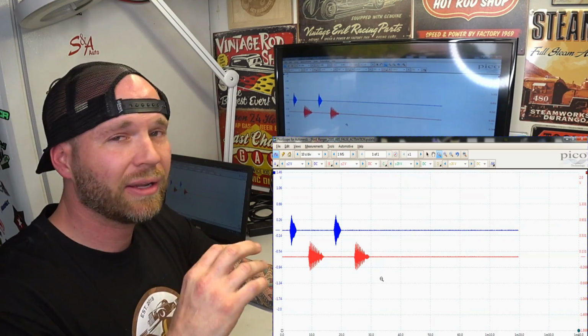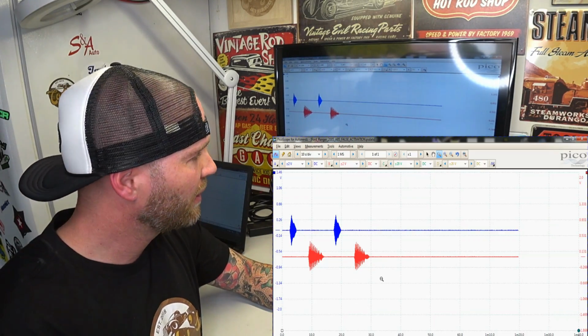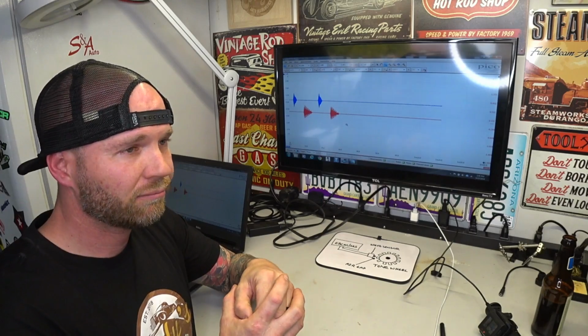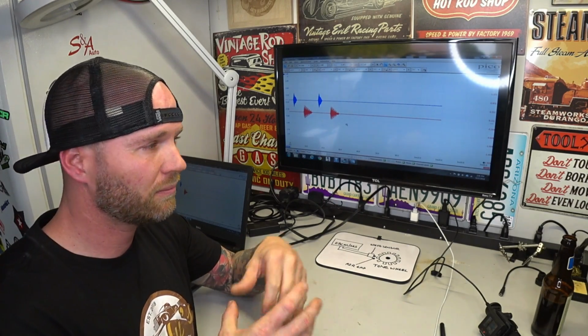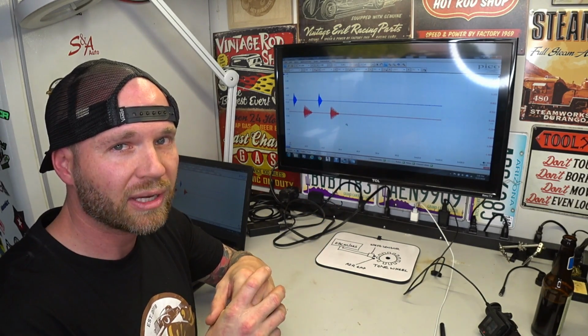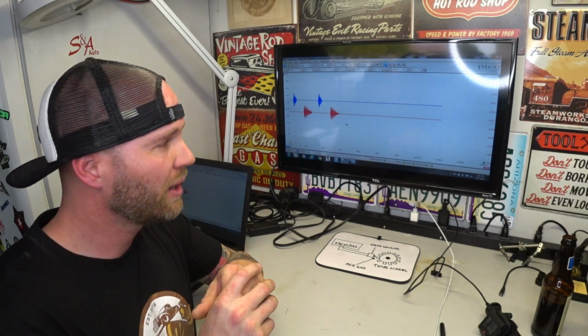I have video, it's pretty shoddy video. I was trying to hold the light, get a capture, and spin the wheel, showing you guys that the tone wheel is actually off-centered. You can see it rotating as the rotor's spinning. So that's confirmed that that rotor is bad, or the tone wheel placed on that rotor is bad. It was just done a couple months ago. The right way to fix it is to warranty out that rotor and replace it with a new one.